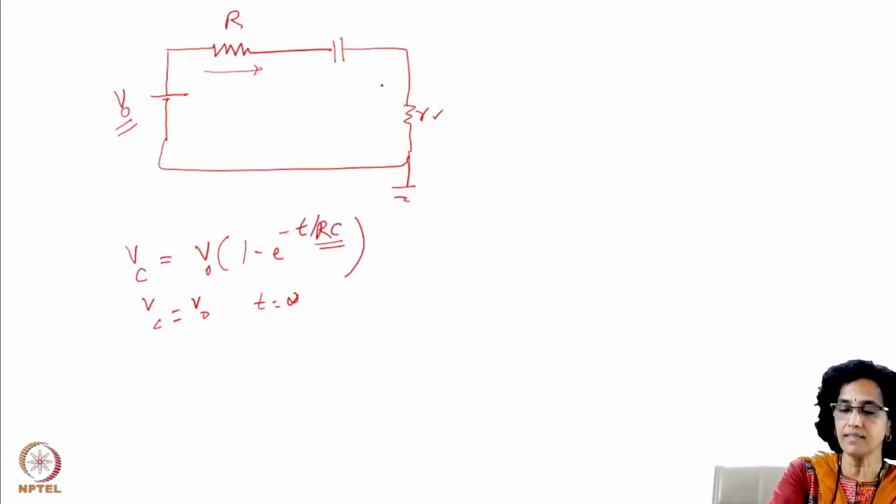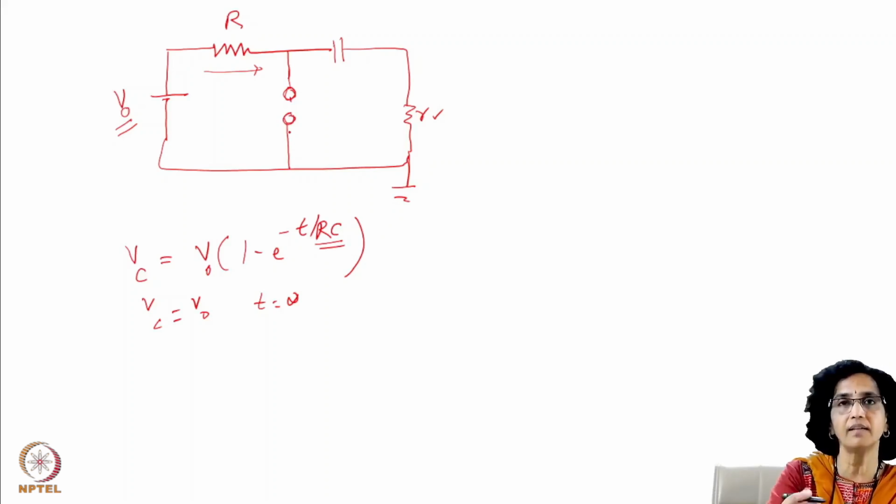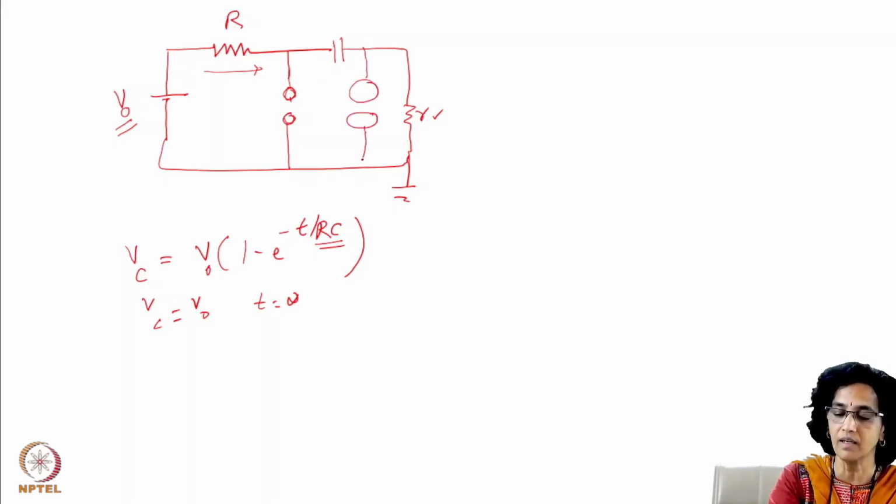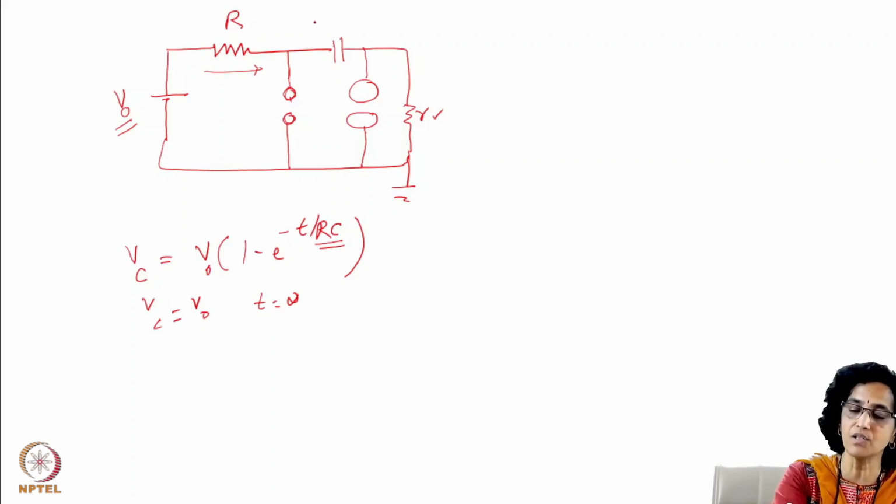So the condenser gets charged, and when it gets charged to the required voltage, we have a switch, which is nothing but a spark gap, basically two electrodes, and the separation between these gaps is so adjusted that it is the voltage that you want the laser to switch at. And so this condenser then switches through a laser load. I'm just showing the laser load as again two electrodes. So once this is charged to the required voltage, the switch closes.